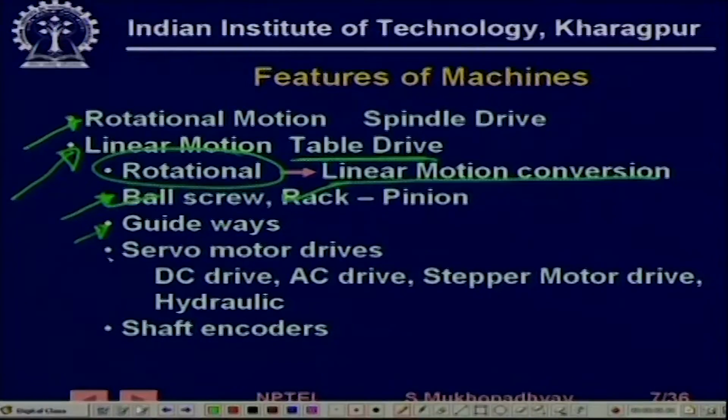These drives that are employed are generally servo motor drives, because you need precise motion control and good transient response. Position control has to be very precise. Therefore, they have to start and stop at the right moments, and sometimes even speed ratios have to be maintained along the two axes for cutting things like surfaces, say cylindrical surfaces, or cutting corners.